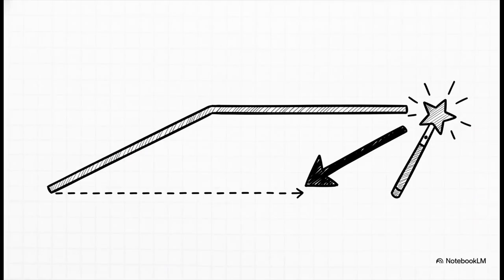And right here is the brilliant aha moment. When a site engineer calculates the total length of a steel bar, they usually start by just measuring the straight horizontal span across the room. But that straight span already includes the horizontal base of our triangle, which is 1d. So, to figure out how much extra steel we actually need for the slant, we take our inclined length of 1.414d and just subtract the 1d we already counted. That leaves us with an extra 0.414d, which is practically rounded to the magical 0.42d. And that is exactly why you simply add 0.42d for every single crank in your bar.